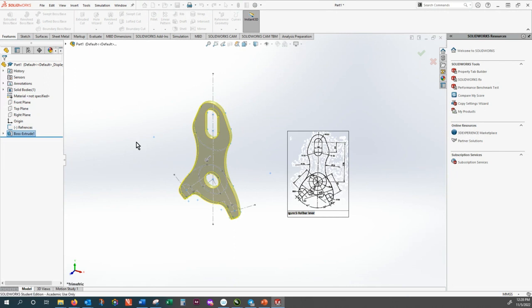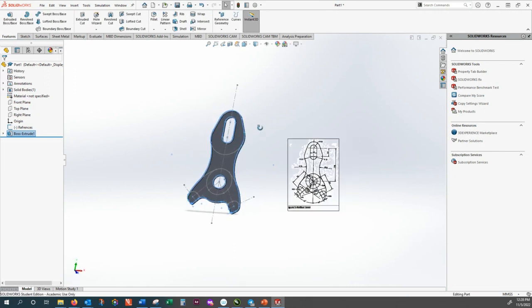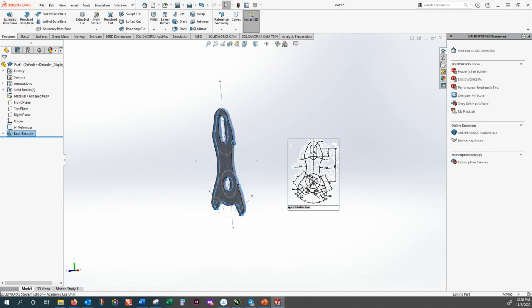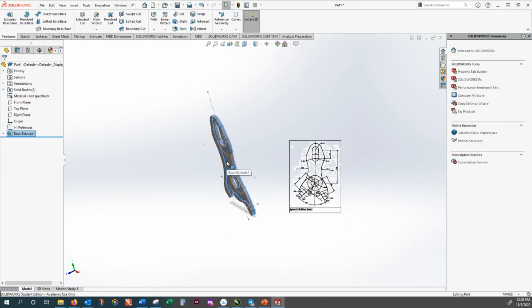All right. So this is not complete. I need to add spot faces here, spot faces there. But that spot face extends on both sides of the object. So how can I do that? A new technique is to construct a new plane. I want to construct a plane which is not sitting on the front plane, not on the back plane, but